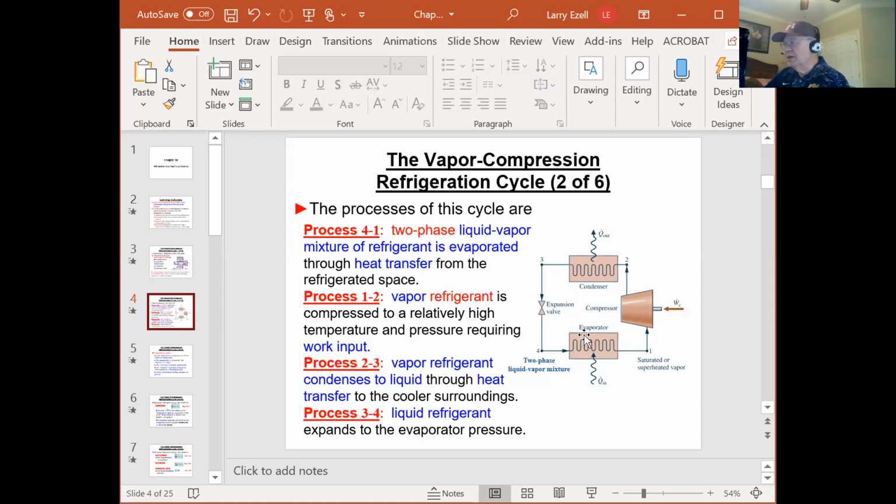And again, I'll have these written down for you. So that's the work of the compressor. By the way, H2S minus H1 is the adiabatic, isentropic work, and H2 minus H1 is the actual work. So we have to deal with that H2S and H1 again, and I'm going to teach you how to make those calculations. I'm not going to do it here; I'm going to do it in the problem solving video.